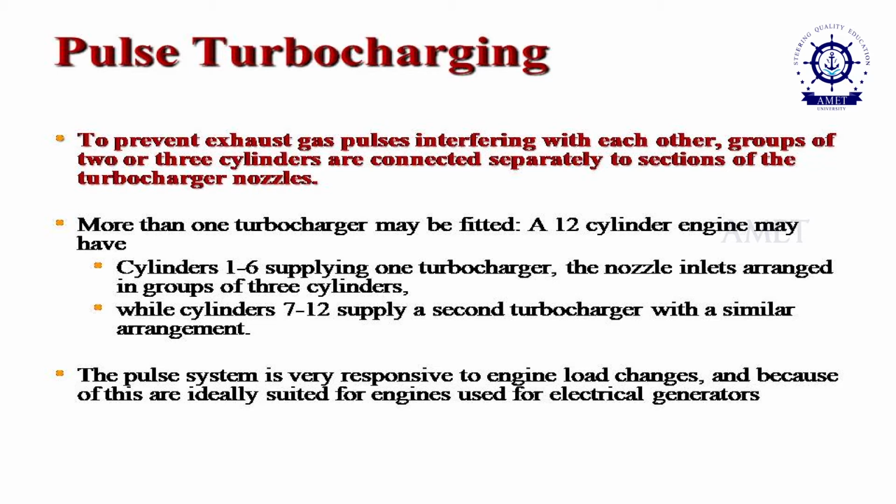When I am sending out exhaust gases, please remember that I have connected many units and the gas is going collectively towards the exhaust. Now, it can happen that one of my units in that common pipe leading to the turbocharger is taking air in while the exhaust gas of another unit is coming out. So, instead of the exhaust gases going out to the turbocharger, it may end up entering the other cylinder. That is a challenge which will be there in a pulse system.